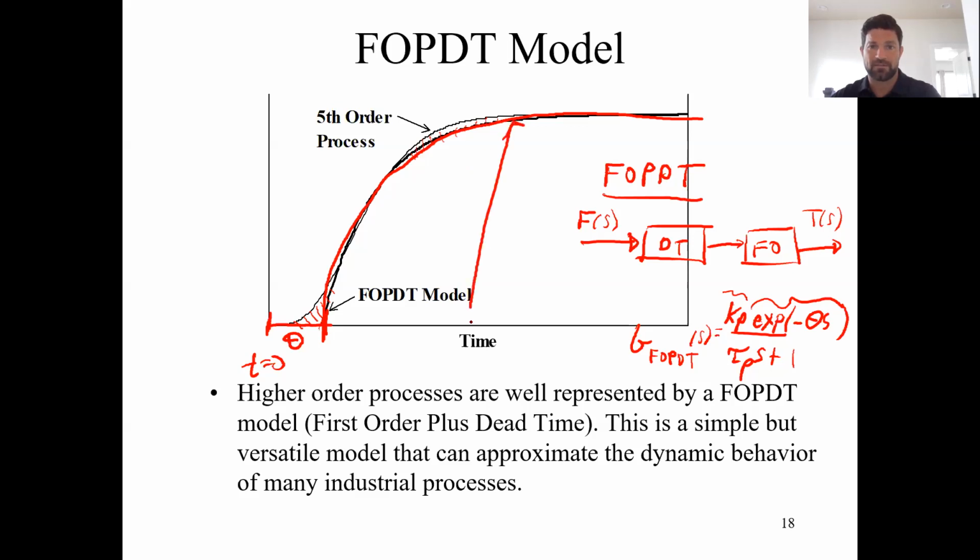This is going to be our step change A times the gain, or delta U times the gain. Then over here, we can look at 95% and 63%. This right here is tau P, and this right here is 3 tau P to get to the 95% mark. And at some point, it's at the new steady state.